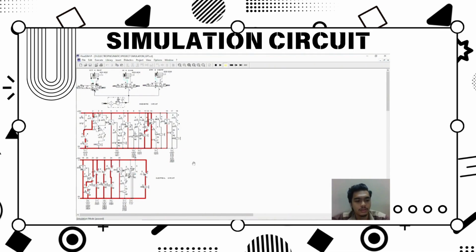After timer -T3 counts for 5 seconds, the timer contact -T3 will close and activate solenoid coil -MB2 here, and then activate the right switching position and allow air to flow from port 1 to port 2. Piston rod -MM1 will fully discharge position for double acting cylinder DAC, and magneto proximity sensor -BG1 will close and the current will flow through relay contact -KF6 and -KF8 in close contact to energize coil -KF7,